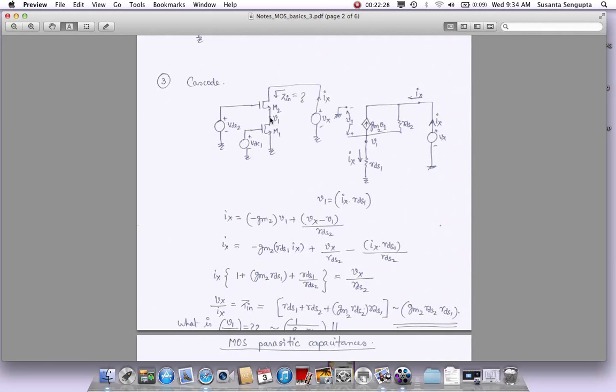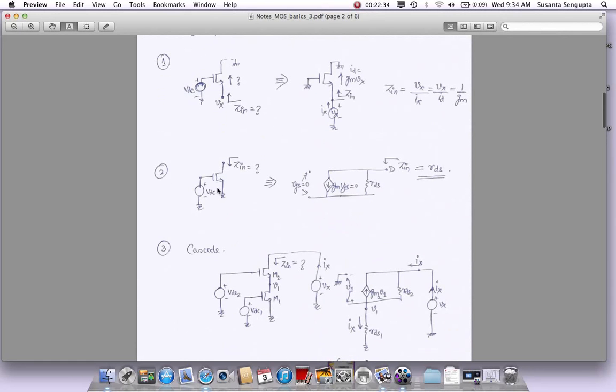But we know that anytime the VDS changes, we have some channel length modulation that happens. So if I come back to this source here, with a constant VGS creating a current that I'm going to use to bias other circuitry, this current would still move based on how this voltage is moving.